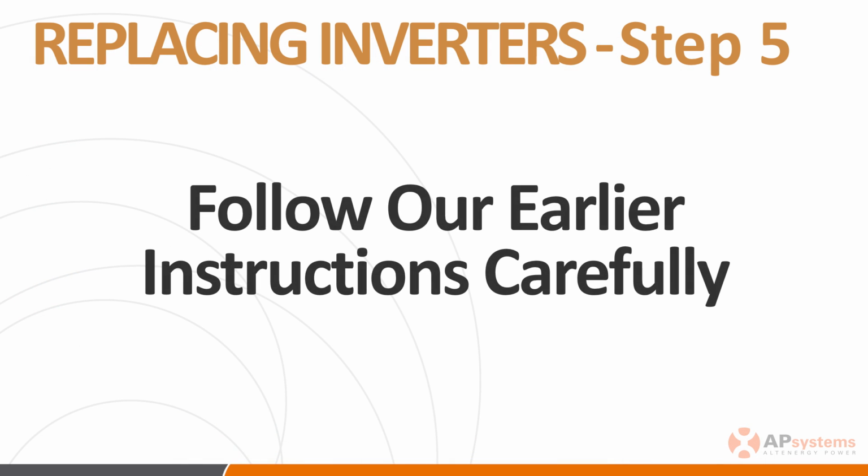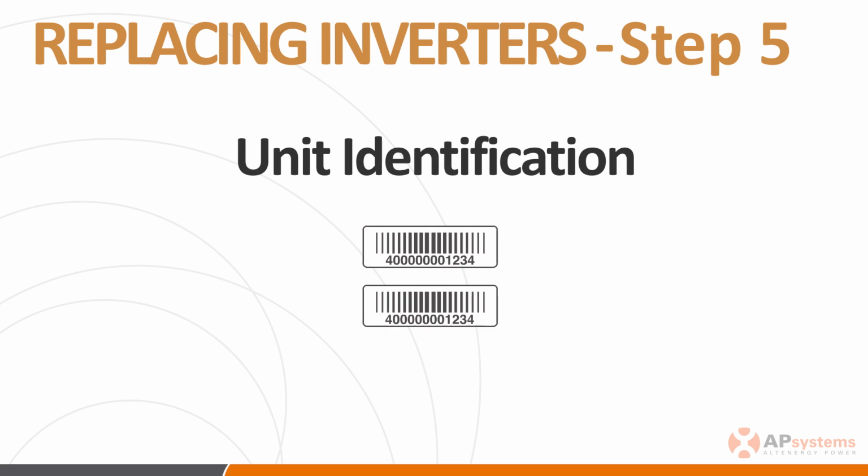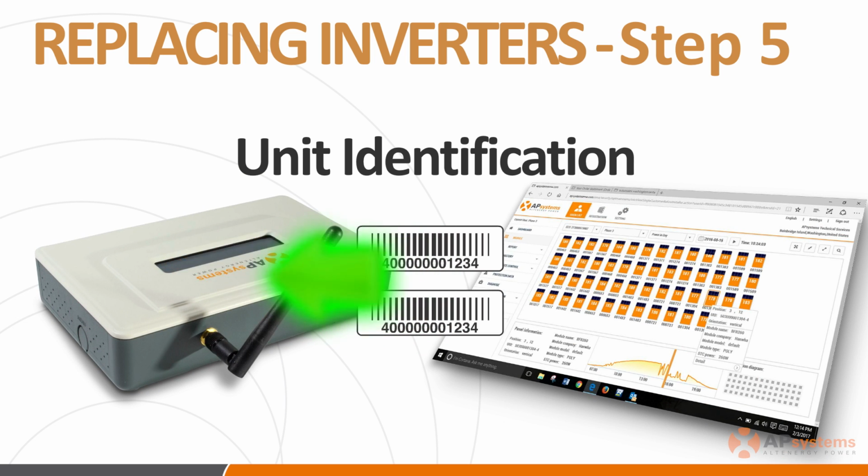Follow the installation procedures we've gone over earlier in this presentation to install the replacement inverter, making sure to change the inverter UIDs in the ECU and EMA to reflect the changes that you've made.